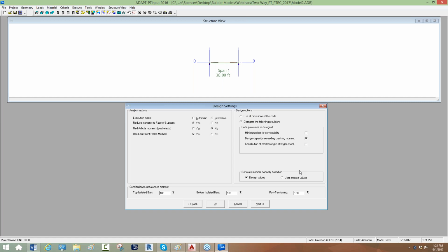If that is your objective, to do an investigative type model like that, the only output that really is geared towards giving you the information you need is a report, which is report block 34 in the tabular report generator, and that block will outline demand moments, moment capacity, negative and positive.